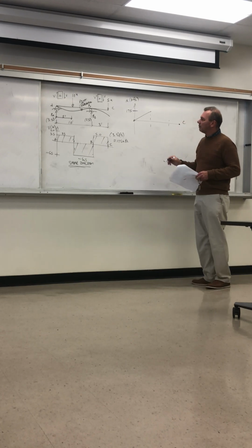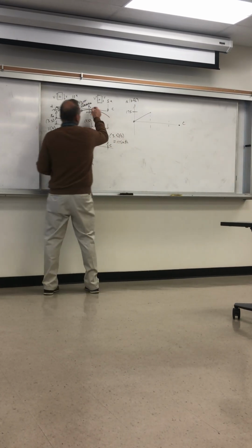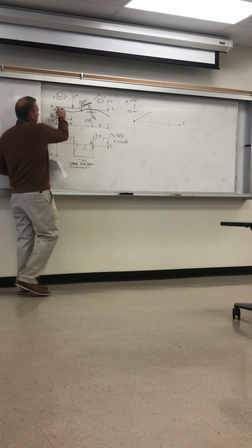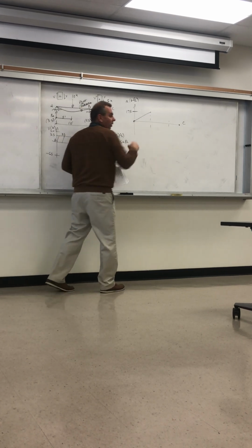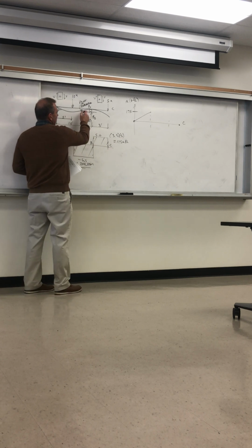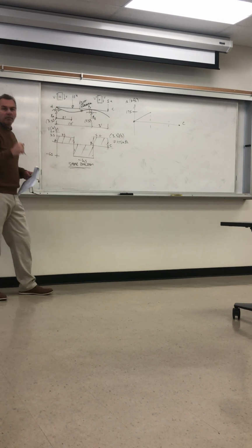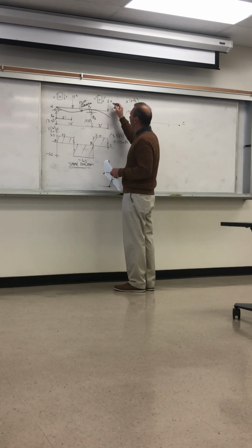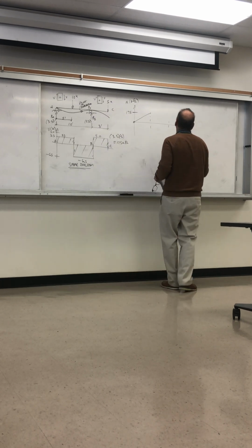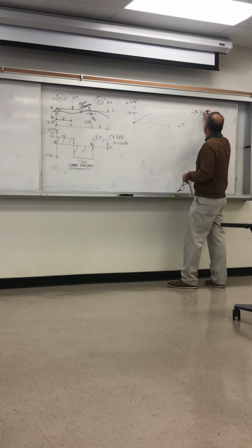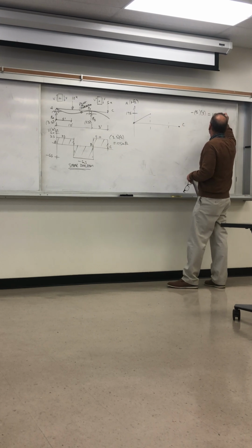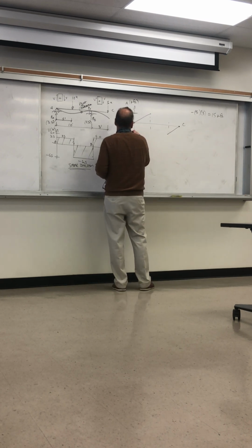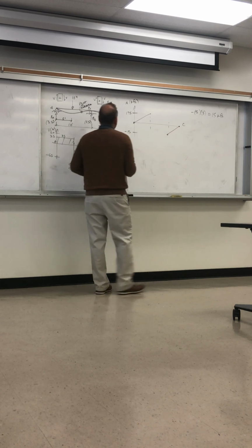This is 0. This is negative bending here. You can see the negative curvature. So when the curvature is like that, negative, the moment will be negative. This is all positive bending, as we've seen from the first part of our sketch. And then there's a transition from positive to negative bending at that point of inflection. The moment right here is just by statics, 5 times 3. That's minus 15. That's this point here. And then we can just draw a line between them.